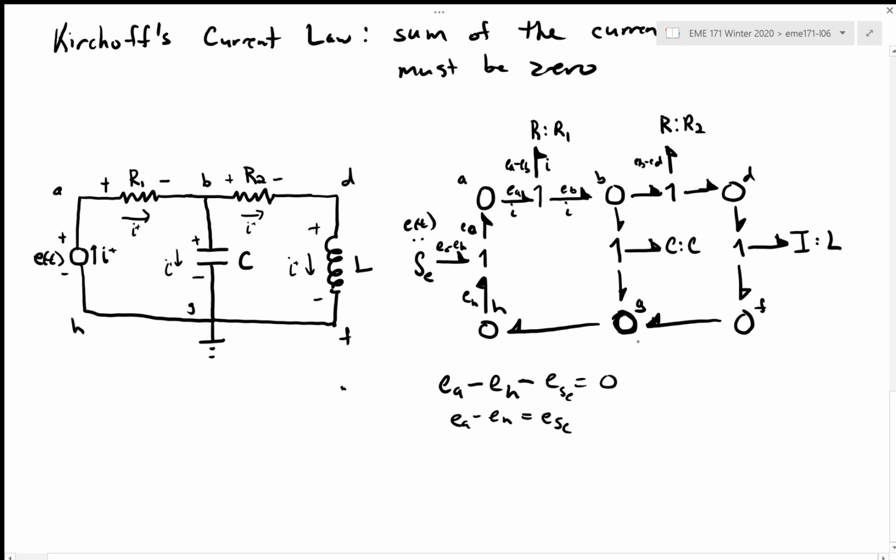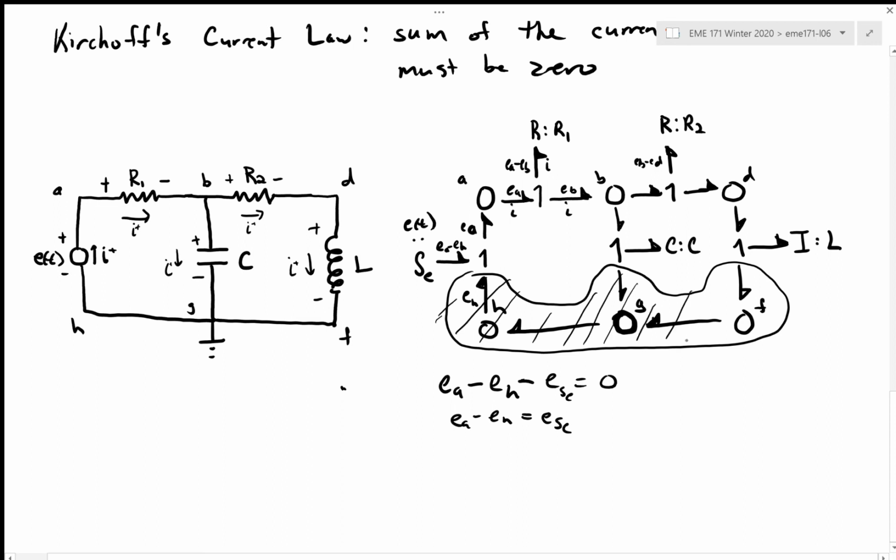And this means that we are going to say that that is the reference voltage, and that voltage is 0. If voltage is 0, well, voltage times the current is also 0. Power is 0. So we can then eliminate that junction G. All right. If I eliminate G, well, G is the same as F, the same as H. I am going to get to take this whole chunk and eliminate it as my reference voltage nodes, right?